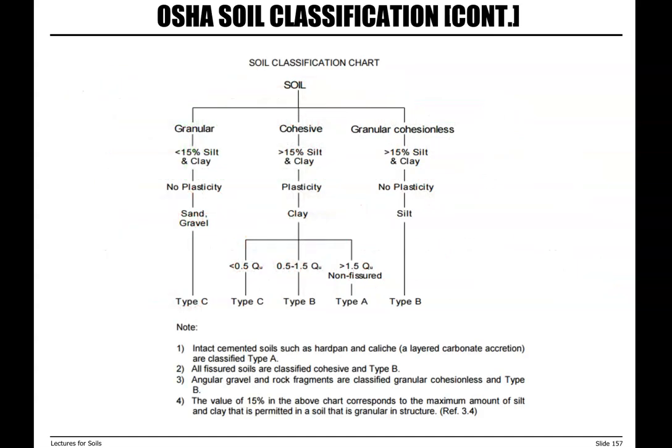So, to summarize OSHA's classification, we have a soil sample using a structural classification. We call that soil a granular soil if it has less than 15% fines.